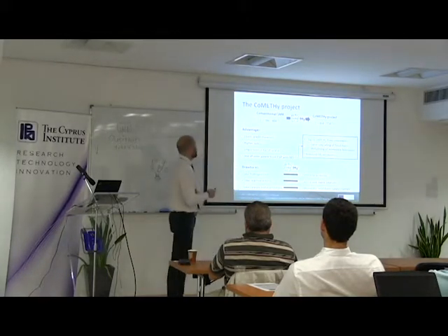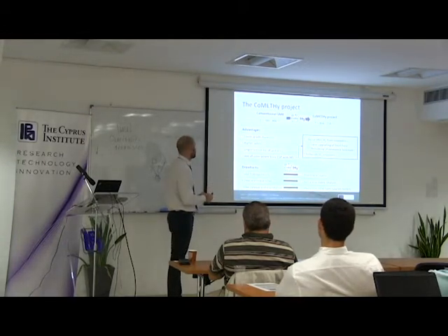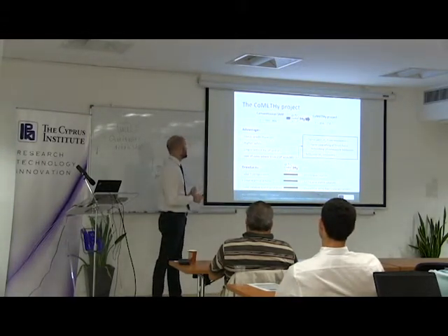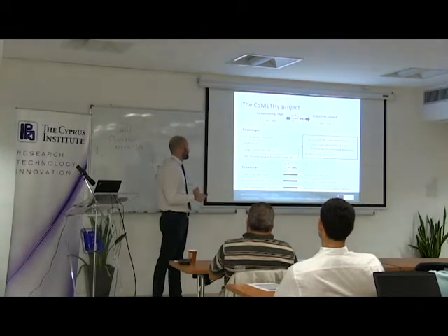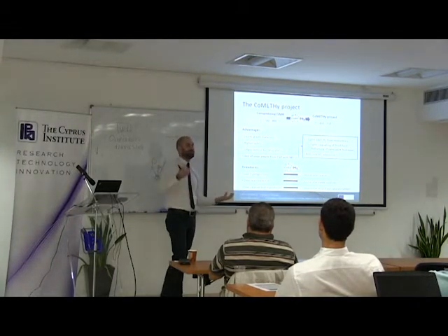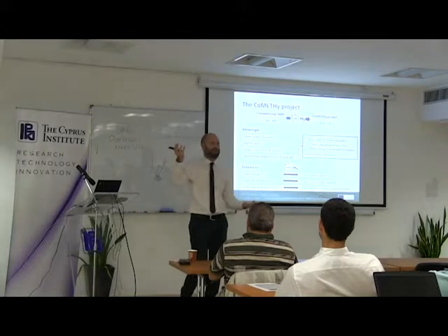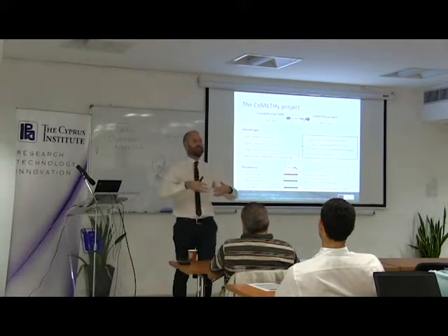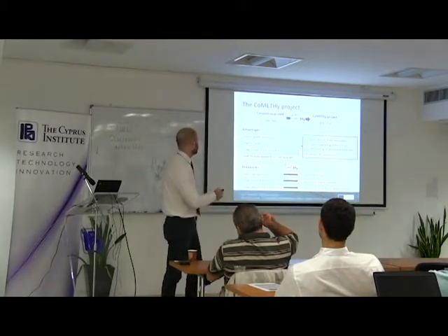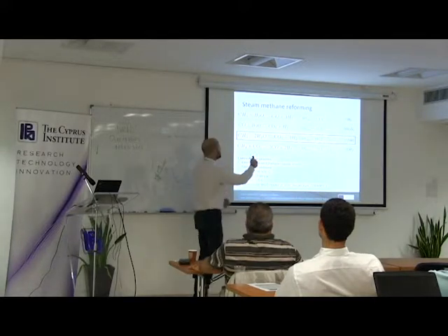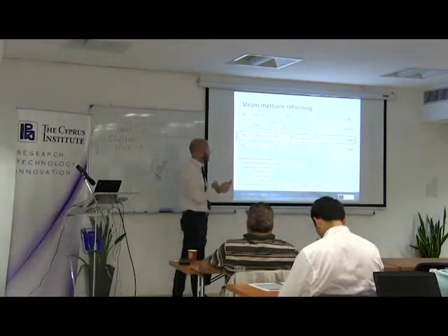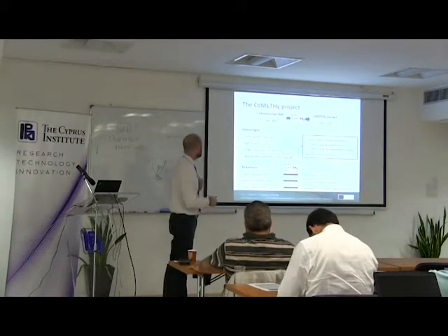So what are the advantages of lowering the temperature? Some of these are trivial. You can use lower grade materials, of course. You have a higher safety of the plant. And this is more chemical: you don't need one high temperature and one low temperature reactor, because you carry out in the same reactor the steam reforming, this reaction, and this reaction, just one step. You save one piece of equipment.